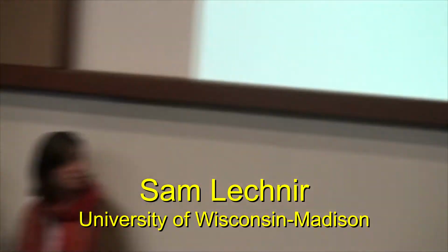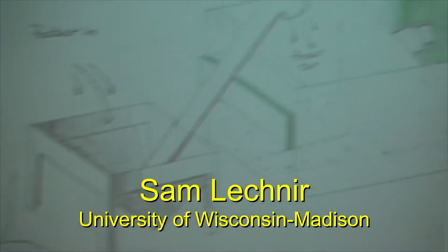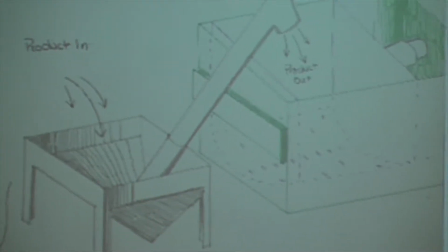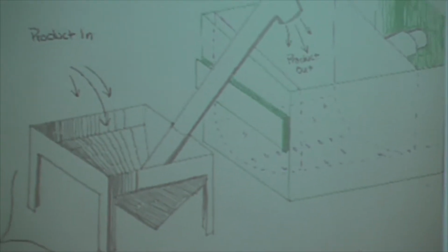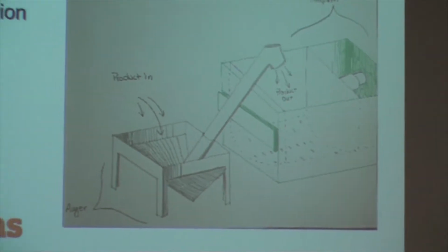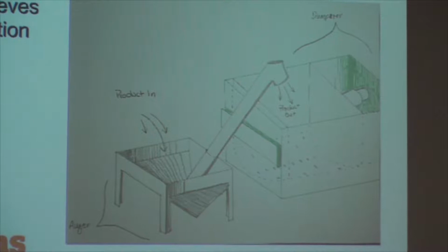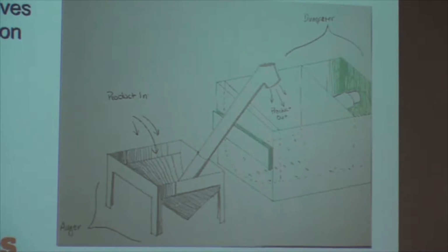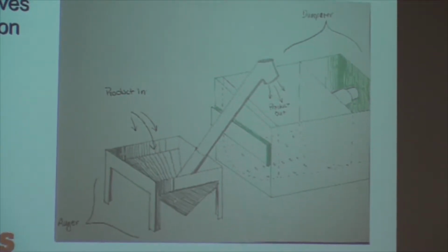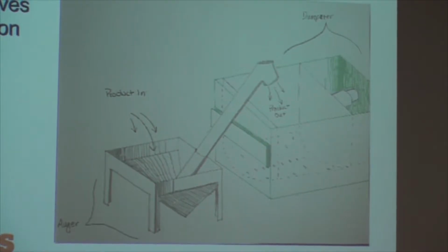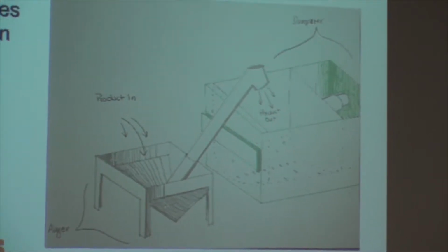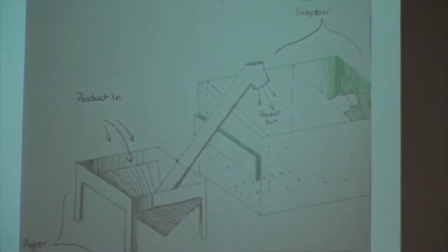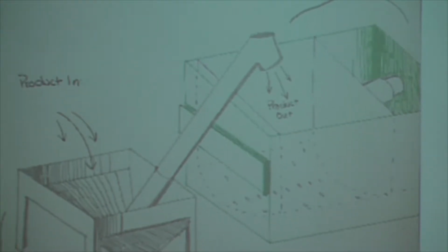talk. So our final design concept is on the bottom right there, and we decided to go with a hopper-auger combination that would go into the dumpster. After our baseline decision, we thought this kind of looks like a gravity box design, as you would find on a farm that they use to transport their grains into other containers. So the auger takes the material from inside the hopper, and it will shoot it upwards into the dumpster with an 8 horsepower electric motor.